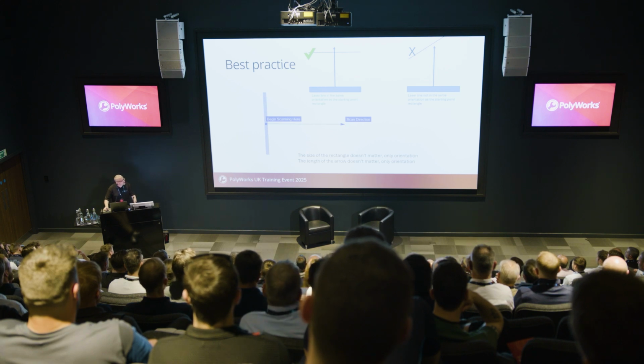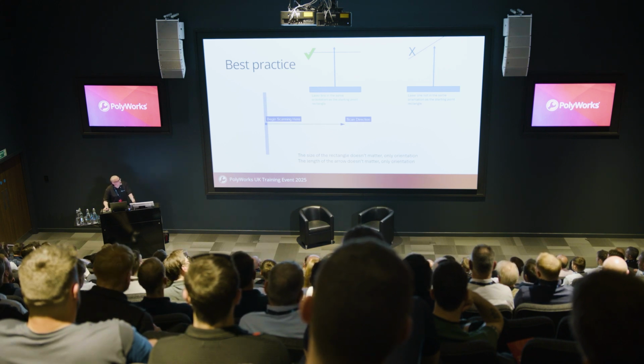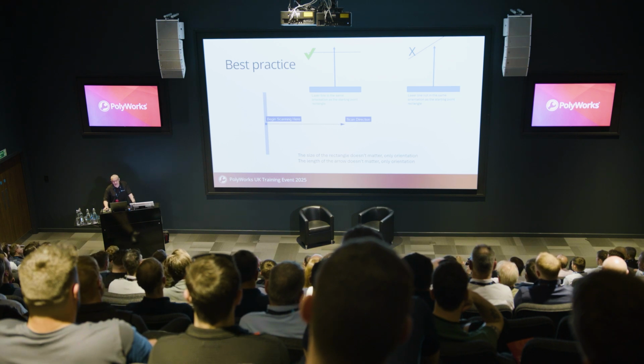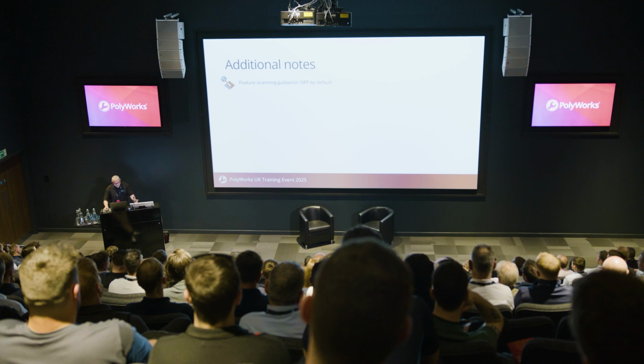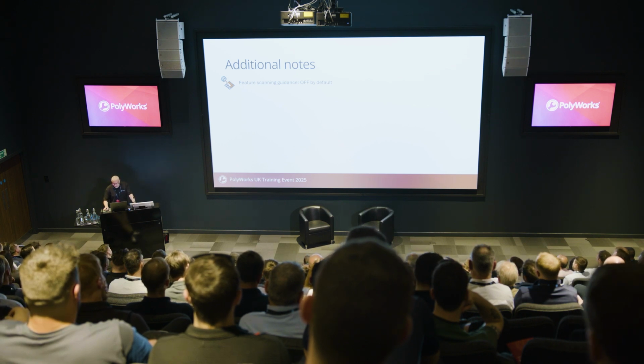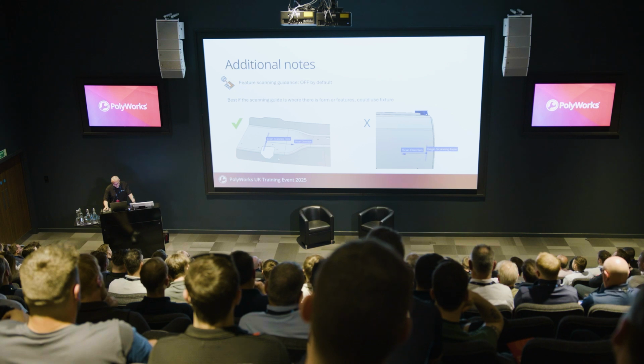Yeah, the size of the rectangle doesn't matter. The length of the arrow doesn't matter. It's all about the direction of the line and the direction we're moving that line away. So the scanning guidance is off by default. We can turn that on in the little bar that comes in the bottom of the 3D scene.